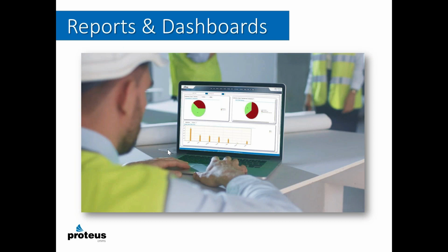Tongue-in-cheek, he says, but in reality, I know for a fact that we have many, many clients that do not have enough resources to get all the PMs done in the time frame that they're scheduled. And again, that's a metric that you want to look at and evaluate. Why am I doing the PM? If I did it, does it keep the system up and running more effectively? If I don't do the PM, if I run to failure, what happens? What's the cost associated with that? There are different costs and different effects associated with different pieces of equipment.